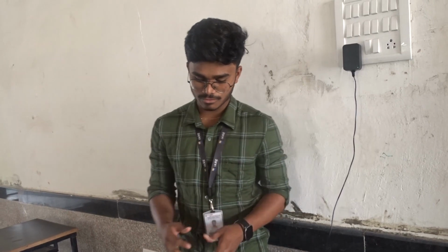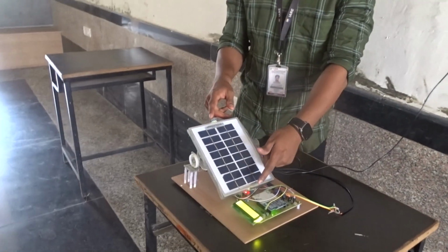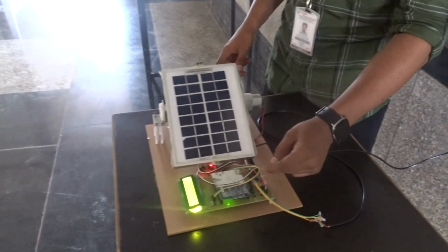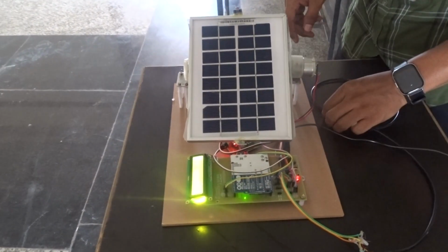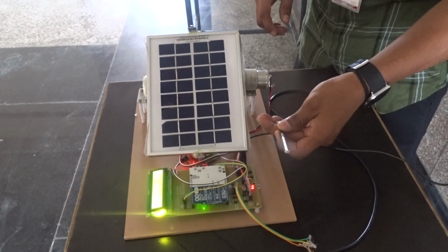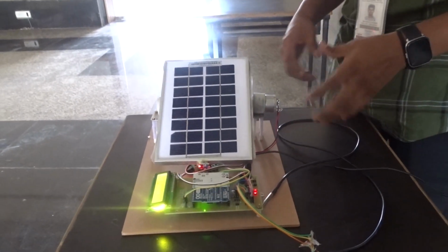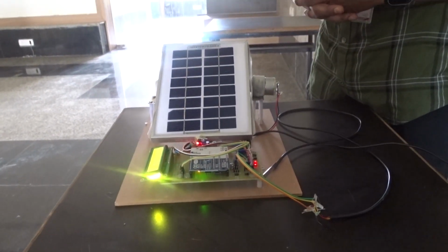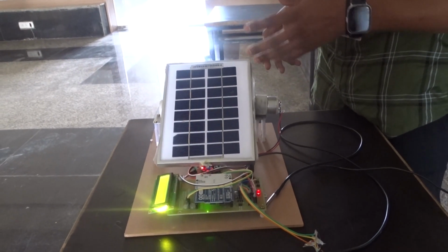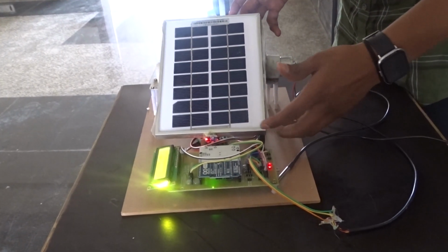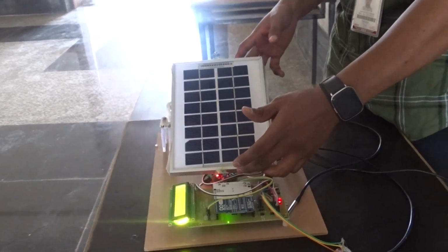Due to the shadow, the current will be reversely generated, so hotspots can occur. To reduce all of those, we are making a project on shadow tracking on the solar panel. Here we are using a panel. We have two LDR sensors, a temperature display, an Arduino board, and a contactless temperature sensor. In this concept, we are using the two LDR sensor concept. That means the panel has two sides: on the right side we have an LDR sensor, and on the left hand side we have an LDR sensor.